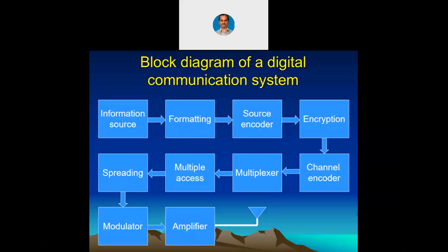A square wave cannot travel in free space because the square wave will be subjected to attenuation in free space. So always a sinusoidal carrier is going to have an easier propagation in free space, not a square wave. Which means the carrier wave should not have abrupt changes from 0 to 1 or 1 to 0. A carrier wave cannot be a square wave.